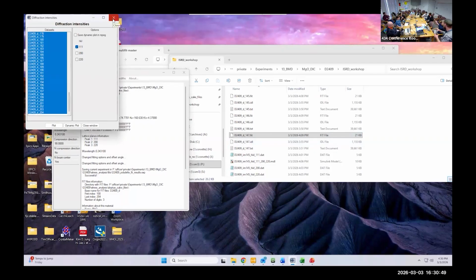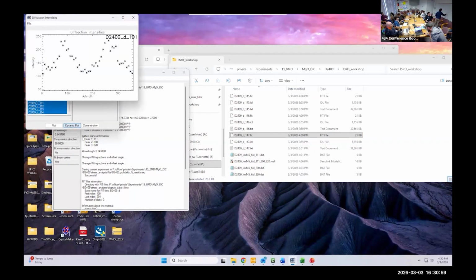So once you have the lattice, how do I show all this? First the lattice, and you have a defect over here. This dislocation slips easily on certain given planes depending on the density of the atoms in that plane. The higher the density, the easier for the dislocation to propagate. So when the dislocation propagates from here to here, it goes off the grain, so the whole grain will change to this shape, right?